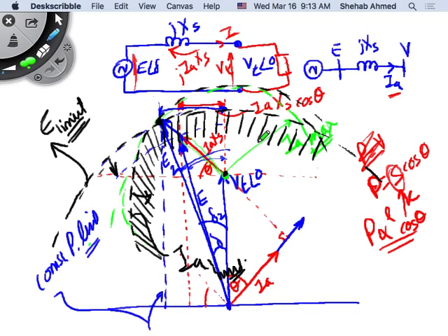So every generator will have operational limits, right? Besides the 90 degrees. Remember we said that the angle cannot exceed 90 degrees. That's one thing, which means angle of what? Angle of E. So E can change here. If I want to continue delivering the same constant real power that I was delivering, then I can move E here. If I move E here, what did I do? This is my new E, for example. What happens here? Yeah, so I changed theta.